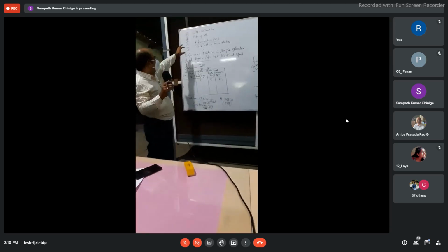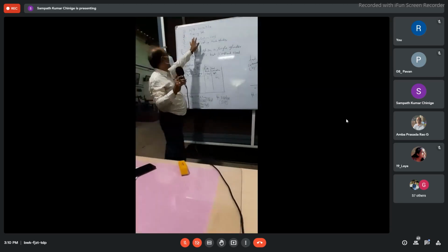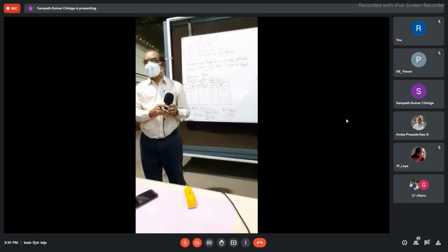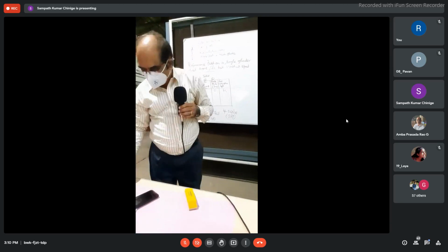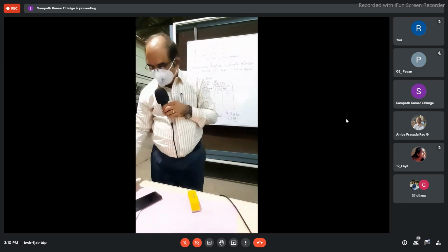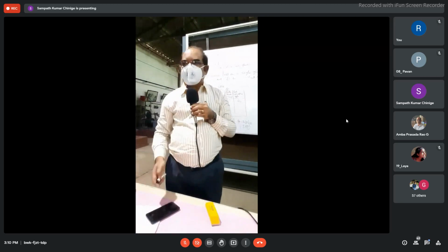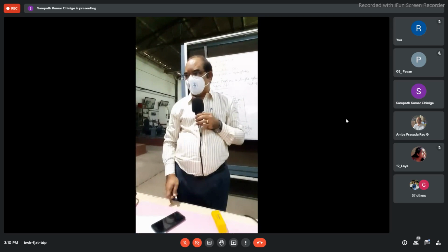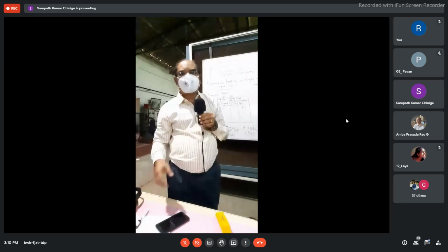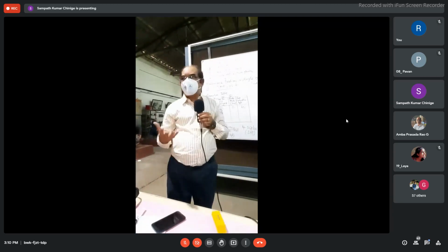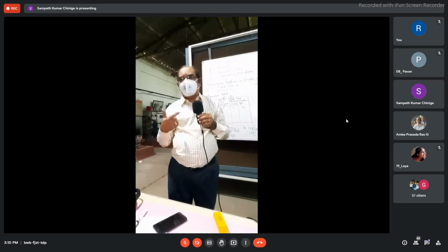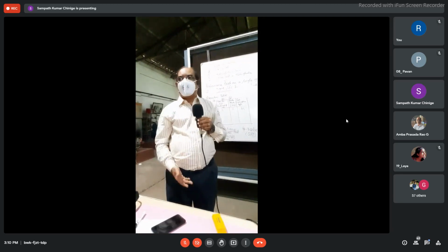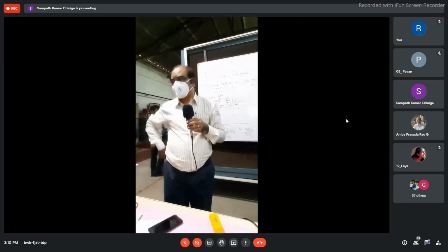And how do we do this motoring test? Let us understand the meaning of motor. Motor means some electric motor. As you know, we conducted the performance test on a Kirloskar diesel engine, which is provided with a DC shunt dynamometer. This DC shunt dynamometer means an external source, an electrical motor. So this motor permits us to run the engine initially. It draws power from the mains, and when required it stores energy as a generator. When required, it works like a motor and gives us some mechanical energy.